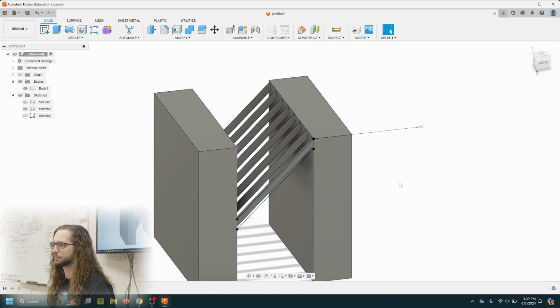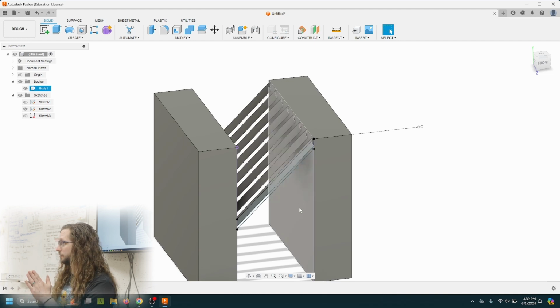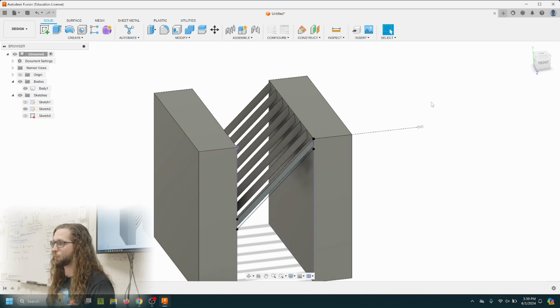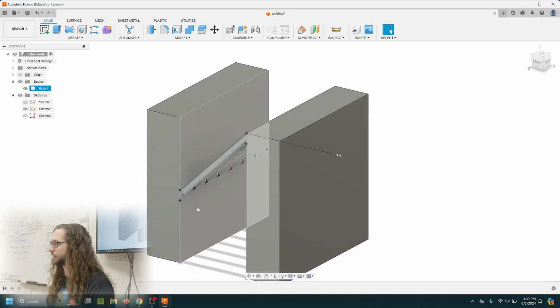So right before you made that into one body, the point at which it joins the plane looks like just a single point, but it becomes the entire triangle once you join it up. Yeah, Fusion knows that that sketch plane is on this face of our model. And that sketch plane and then where it ends up, which is over here, are also on the same plane. So Fusion is smart enough to know that those things are touching, so we want them to join.